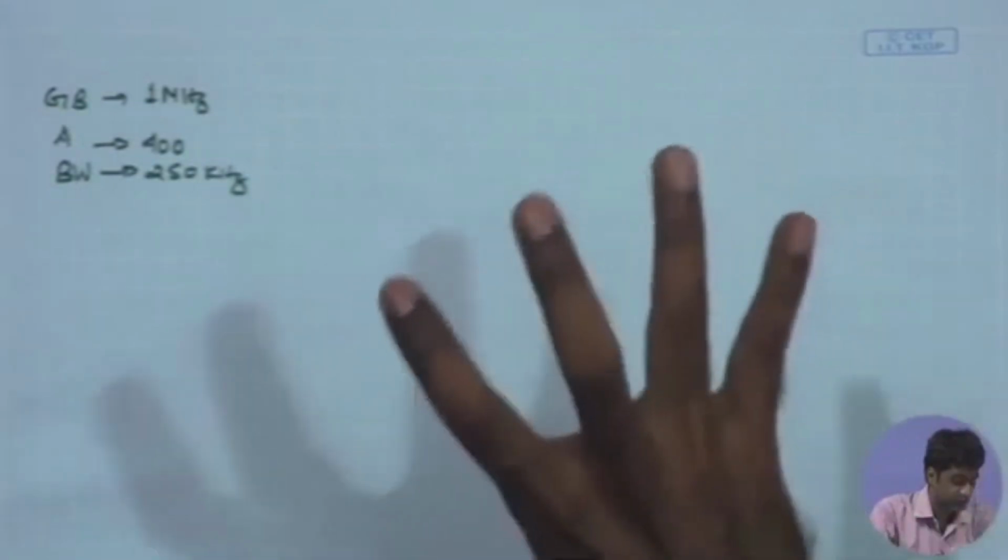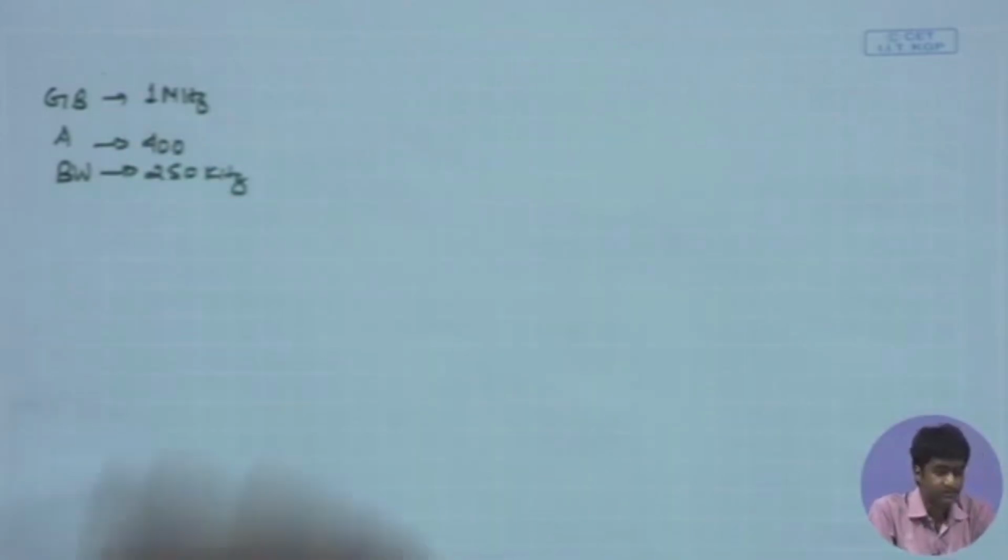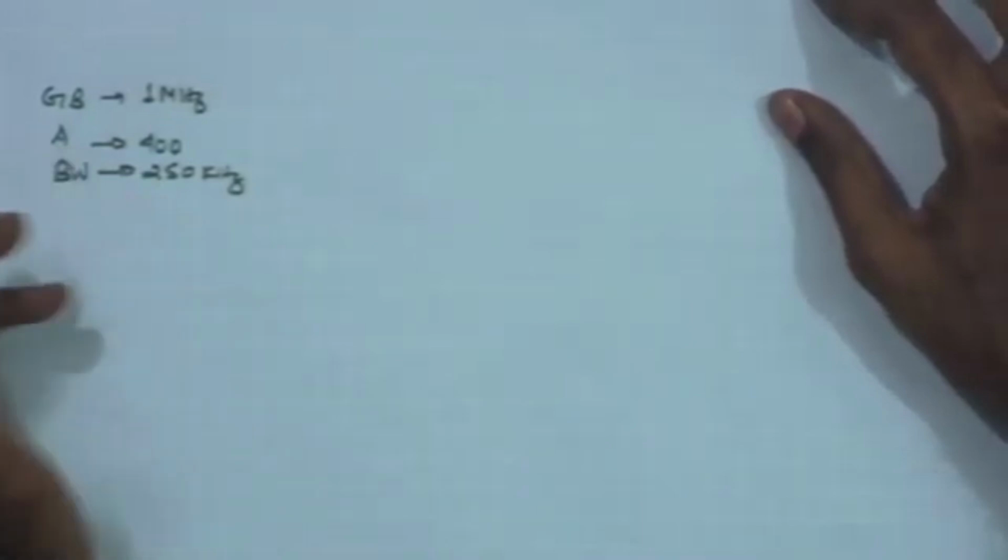So, these are the values we estimated, and based on these we need to look into the design of the comparator and specify first of all the sizing depending upon the gain and bandwidth values. Also, one of the targets would be to minimize the bias current, because ultimately it is an area and power constrained design, where we are supposed to minimize the area of the single channel acquiring the biopotential, and along with that we are also supposed to minimize the overall bias current in different analog units.